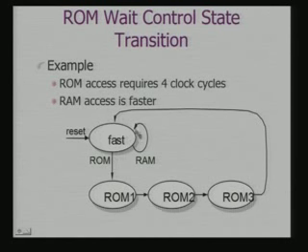If it is a RAM, I shall always be in the first state. If it is on the ROM, I have to take care of 4 states. So, my wait signal should be low, if it is active low, for 4 states, so that the system waits till it gets the data from the ROM. So, this is basically my control logic defining FSM.